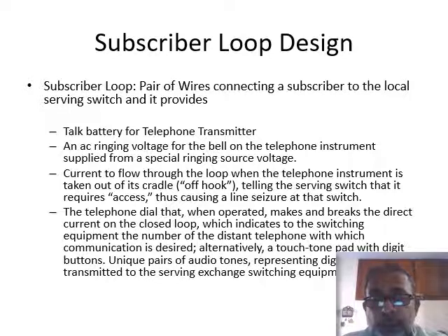Actually, the whole telephone line from the telephone exchange to the telephone set has minus 48 volts on it. And how do we get that minus 48 volts? From a DC power plant consisting of batteries, a large battery bank which is placed in the telephone exchange.